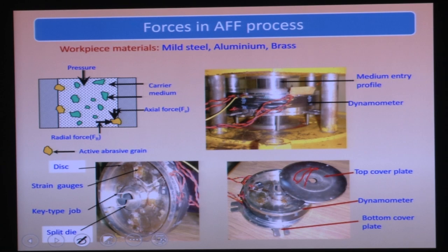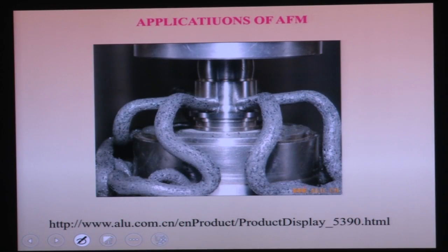Like in a drilling operation, by the tension and compression of these strain gauges, you can calculate what the radial forces are. So these forces, radial force and axial force, can be measured experimentally.